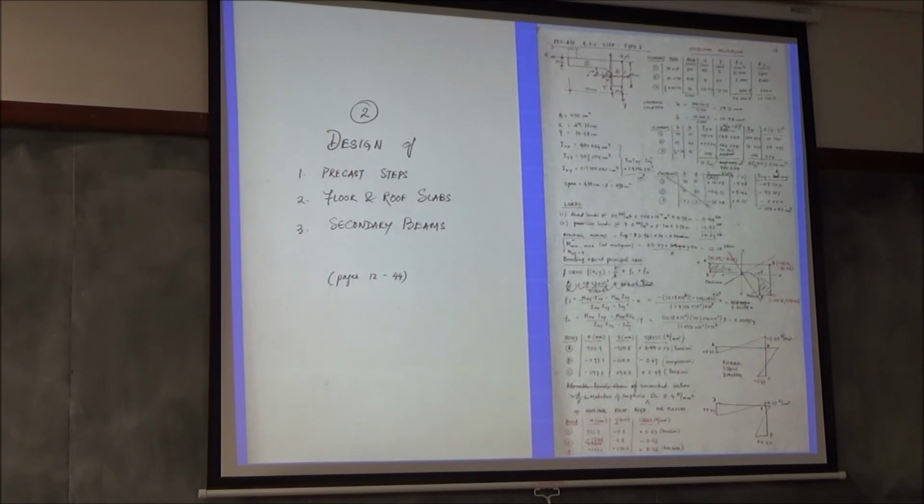Okay. So first, you've got some rough proportioning, but you've got your material to start doing the design. First you get rid of the things which are statically determinate more or less, and you don't need to do frame analysis. So the slabs you can do, the steps you can do. So just to show you, the step is interesting. We said we'll do precast those days. But then it's an L-shaped step, and we said we will treat the whole thing as one element.